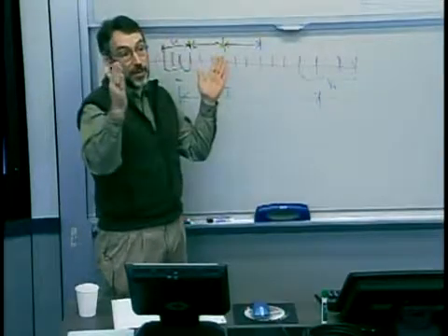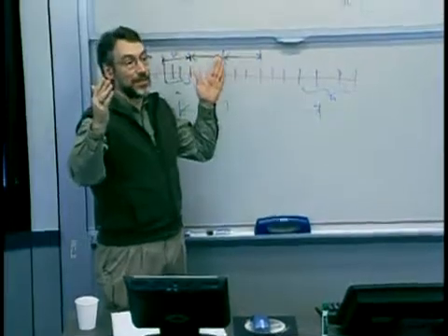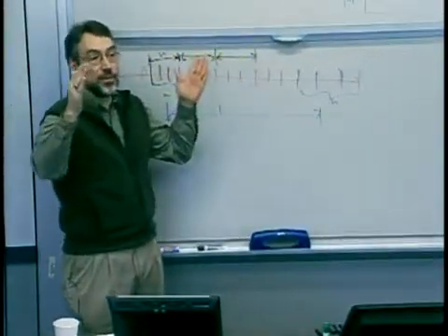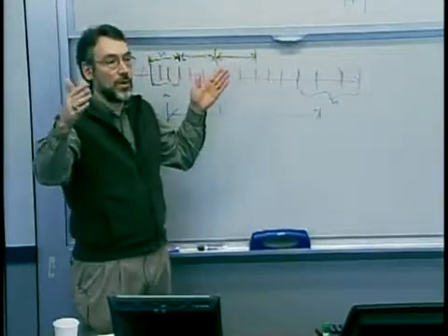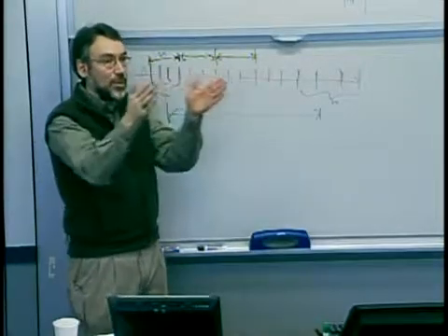Well, let's see. If you go from 3 sigma to 5 sigma, you increase the control limits and you make it less sensitive. You have to have even more extremal points. So in that case, you've decreased the sensitivity of the chart to false alarms. So in that case, you would want to